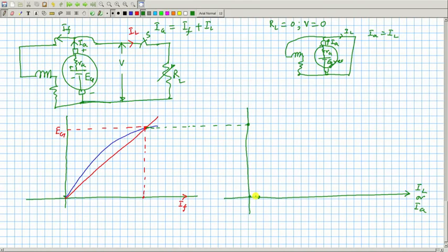So, one thing I am telling, the other extreme point in this particular case is so obvious that I can make it out: this final current will be this E residual, this much voltage E residual, divided by R A. And there is no bifurcation of current here, it is shorted. This I A is I L, it will be like this. Now, the question is, in between then what happens? It is like this. So, this is the no load voltage, this point, we say no load voltage or open circuit voltage.